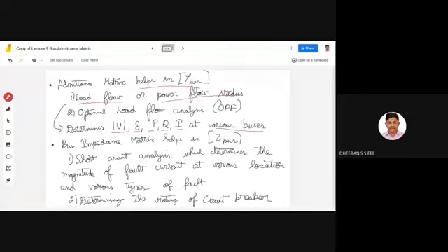For solving with those computational methodologies, you need some parameters. Those parameters are determined through these power flow studies. Those parameters are nothing but your voltage, load angle, real power, reactive power, followed by your current. Okay, so this you can do with the help of your Y bus matrix.